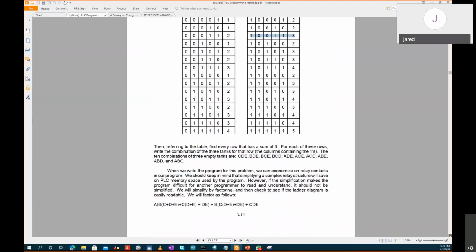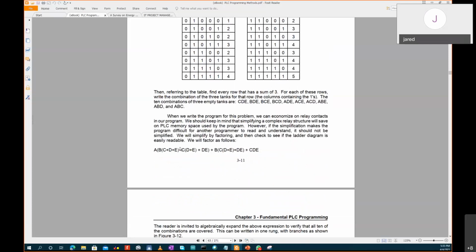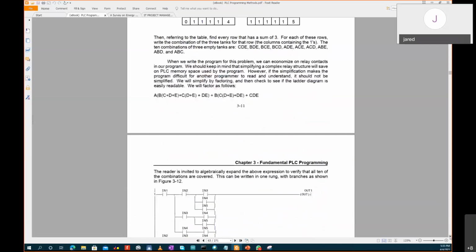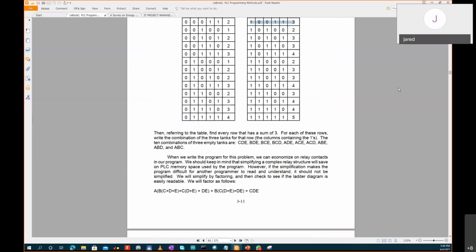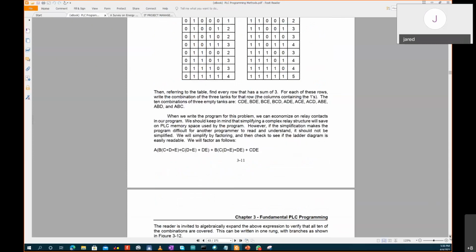And once you have all these combinations, they are going to be ORed and ANDed. So there's something we call K-map, which is used to reduce the logic inputs. If I'm giving you an industry like EABL where you have even 100+ sensors, developing a logic will be very complex. You need advanced tools to develop that algorithm, because if you approach it the way it is, like here, it will be very cumbersome. Even the logics will throw you out. So sometimes you have to simplify the logics.